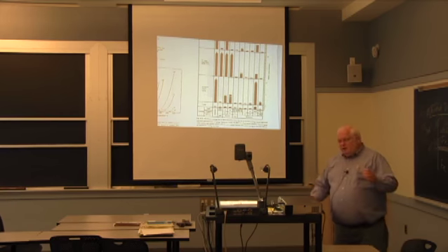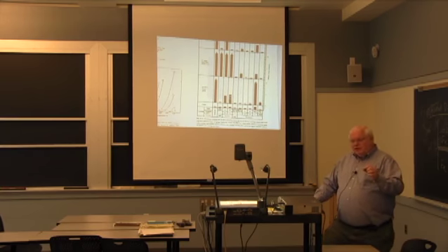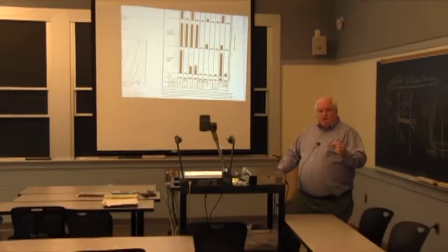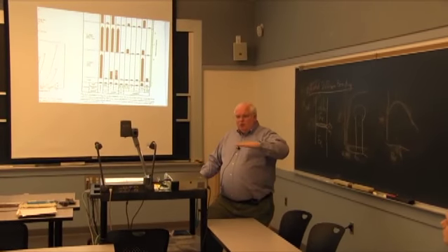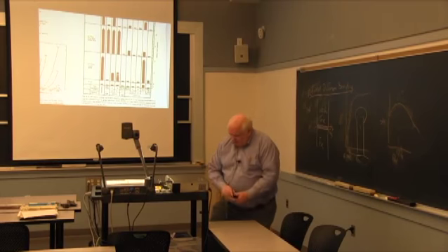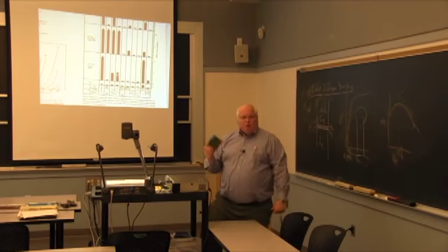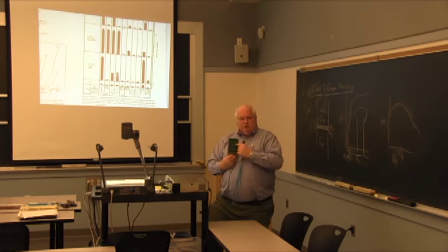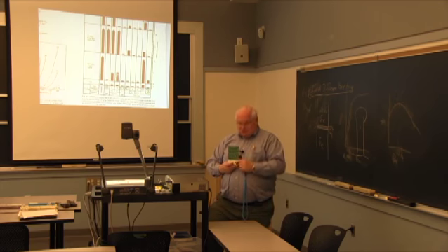So there's a couple of different wetting tests. I may talk about the different ones later, because wetting time becomes important, particularly when you're trying to do a printed circuit board and you put the little solder paste on top of some circuit board, might look like this, and you've screen printed on a solder paste. This one is pre-tinned. It's copper with electroplate of tin on the surface, and you're going to melt the solder to the surface. And this is old, it's lead tin solders.